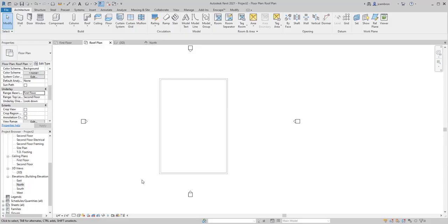But essentially, an in-place mass is kind of taking Revit into sketch mode, right? Sketch mode is something we're familiar with. That's where we can create something without actually affecting the model in a live way, during a live session. So doing the in-place massing takes us into sketch mode, and it allows us to model something using just geometric shapes and forms, right? Up until now, everything has been pre-assigned.